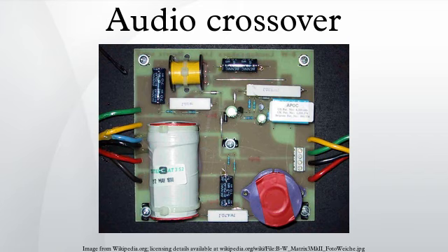A related approach is to shape the main cone with such profile, and of such materials, that the neck area remains more rigid, radiating all frequencies, while the outer areas of the cone are selectively decoupled, radiating only at lower frequencies. Cone profiles and materials can be modeled in FEA software and the results predicted to excellent tolerances. Speakers which use these mechanical crossovers have some advantages in sound quality despite the difficulties of designing and manufacturing them, and despite the inevitable output limitations.